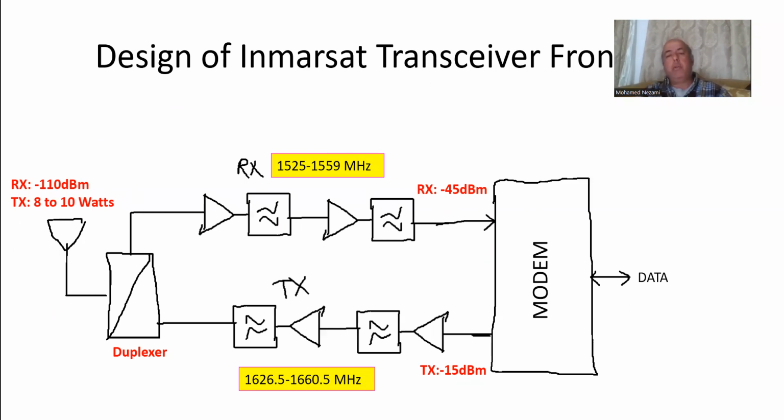Perhaps next session I will come back and actually look at putting a baseband section in here, a generic baseband section, not necessarily a BGAN waveform. We could just put in a QPSK or a QAM and observe such parameters as the error vector magnitude, the spectral growth on the transmitter, and so forth.